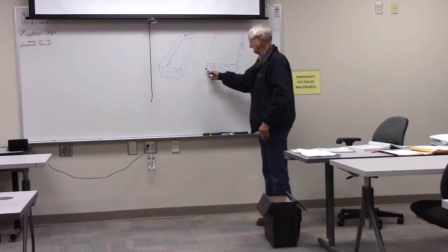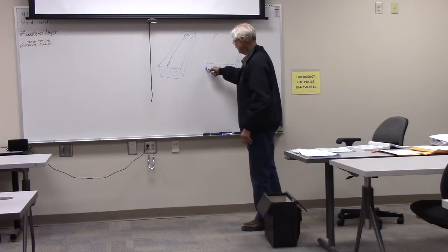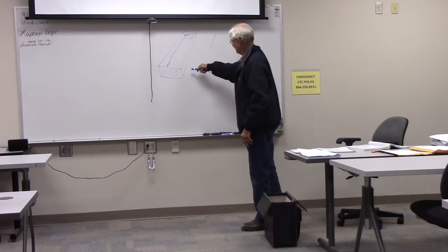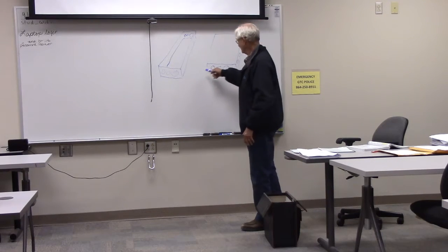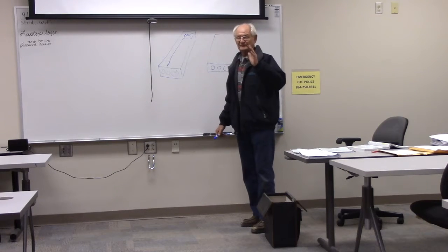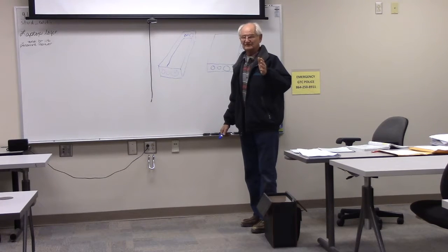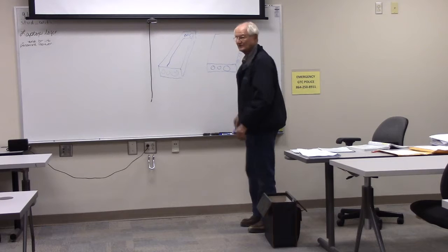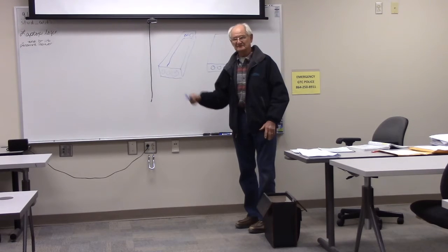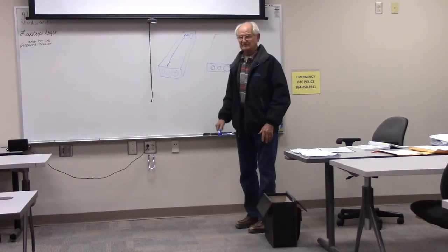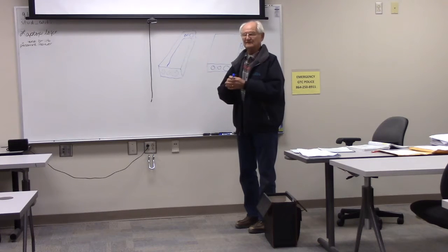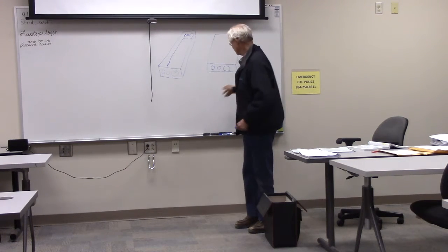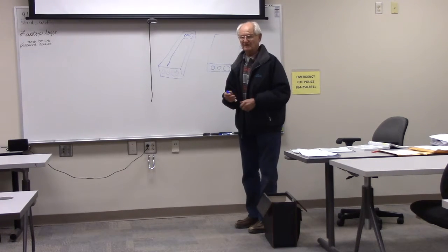So say if it had 2 or 3 more pipes out here, say if it had 5 1-inches, you'd have a 3 inch, and 5 1-inches would be 8 inches, and it'd be times 8, and 6 times 8 is 48. You'd have to have a 48-inch box. It would just get exponentially bigger as you added conduits in the same wall.